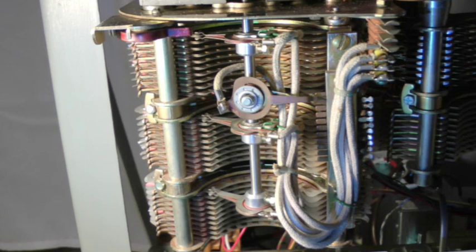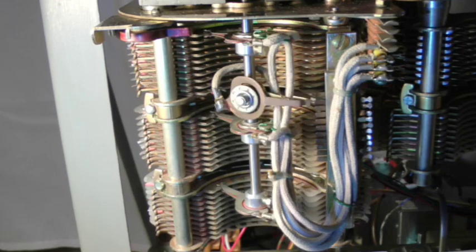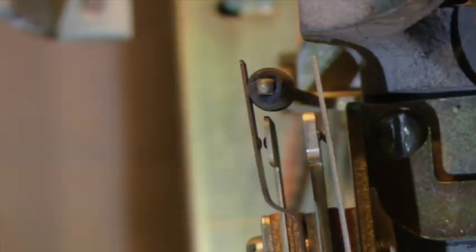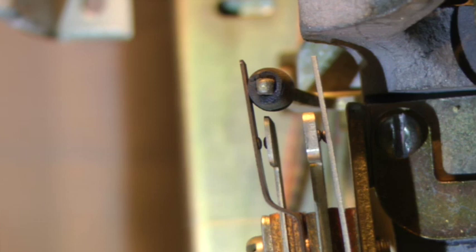The horizontal wipers rotate with the shaft and will come to rest on the second set of rotary position terminals. The rotary interrupter arm operates, closing make contacts 3 and 4 and opening break contacts 1 and 2.